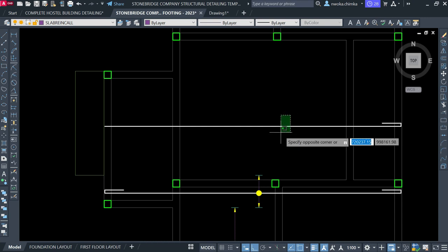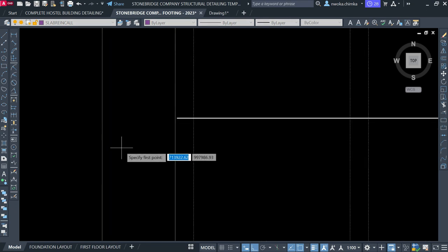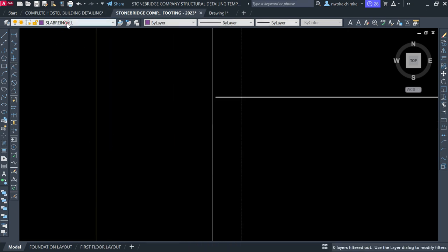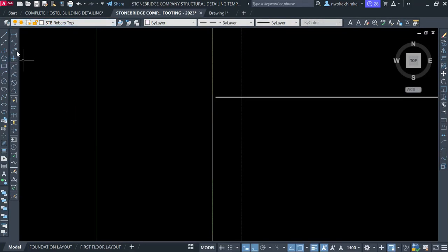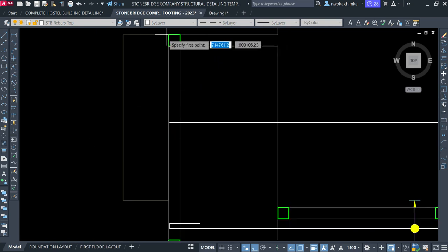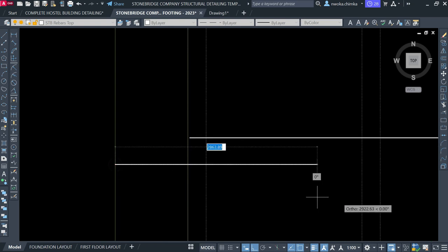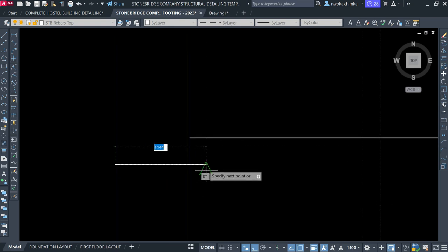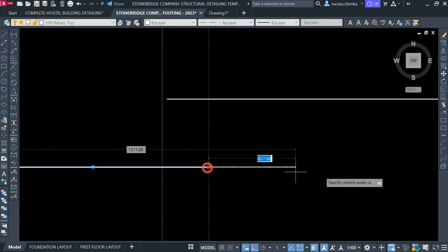And so since this one is a bottom bar right now, I'll have to stop this one here and then bring in a top bar, as you can see what I'm doing right now. I'll come here right now and choose slab rebar top, and then draw my top reinforcement here, which, since this is a cantilever, carries its load at the top. So I'll come here right now and then click here first, and then click on this place right now and type 600, which is my lapping, 600 right now, enter.